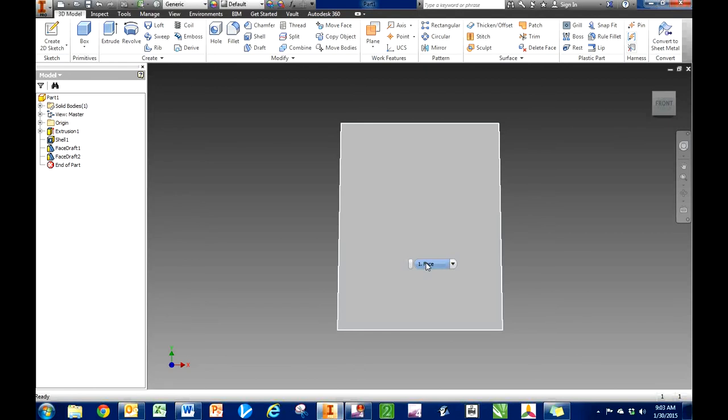The same thing is true on the inside here. Everything is drafted in towards the top so that the mold on the bottom side that's on the inside of this pulls out nicely. And this is now our part dimensioned correctly, and we have a 1 degree draft on all the inside and outside surfaces so that it easily pulls away from a mold for plastic injection molding.